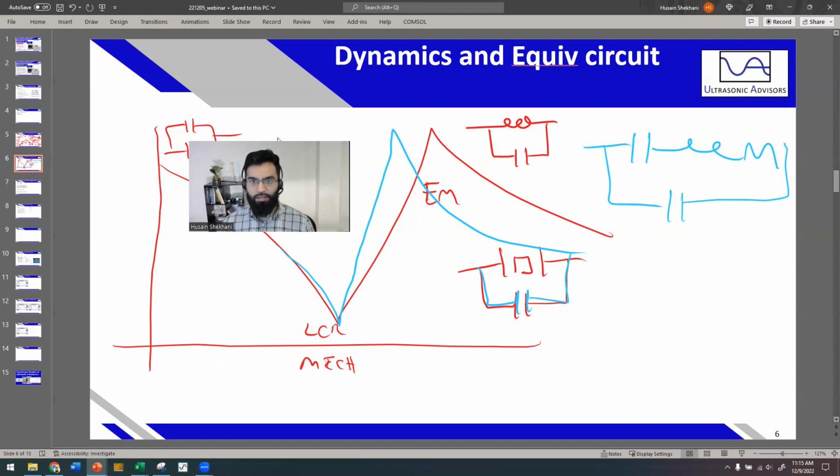There's a lot more to say. This is obviously a simplistic model of a complex device. So it is missing some things, but it tells like 95% of the story, and it's extremely useful for understanding. And if you wanted to, you could add multiple modes, like multiple LCR branches to represent many modes. But in particular, we're just considering one mode of operation in most ultrasonic transducers, especially power transducers. So it's not really important or valuable to add extra branches.